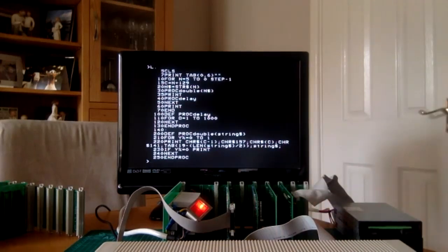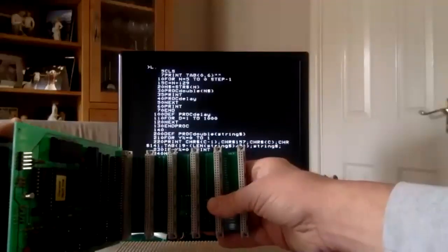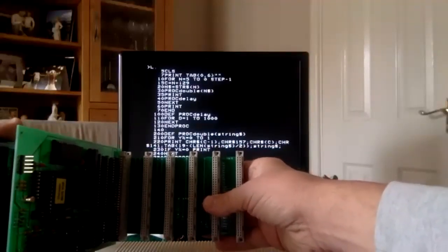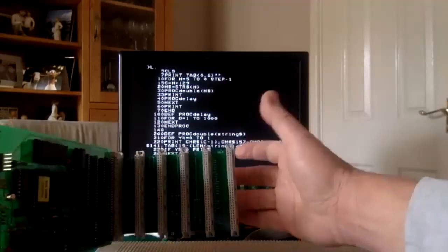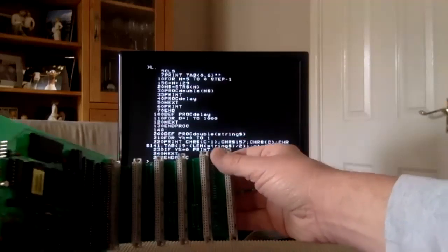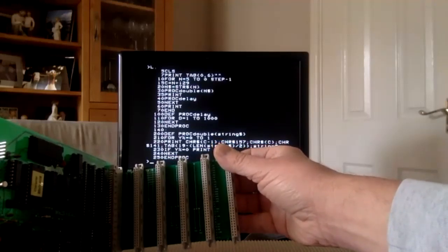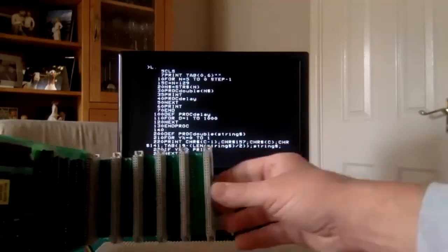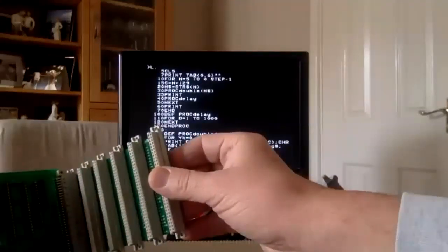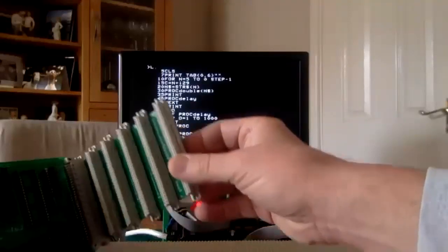When it gets to the System 5, I've got a new backplane for that, which is a buffered backplane that takes the CPU frequency. It's a 24 megahertz, I think, crystal on the CPU card. And it's transferring a range of frequencies across the bus, 12, 8, 6, 4, 3 and 2 megahertz that can be picked up, and that can be used to synchronize the new VDU card. It's got onboard clock generation, but it can pick up through the CPU card as well.